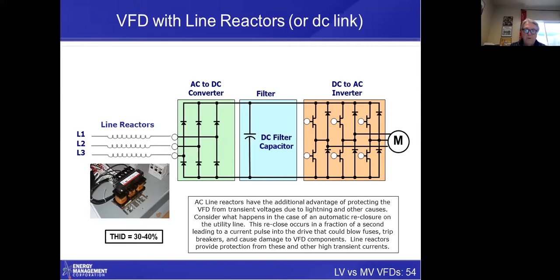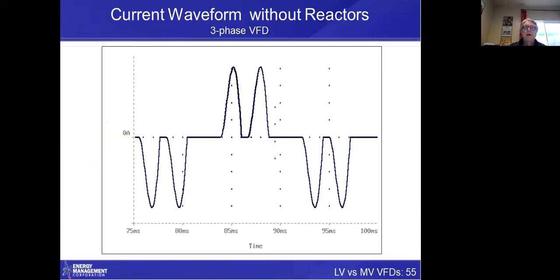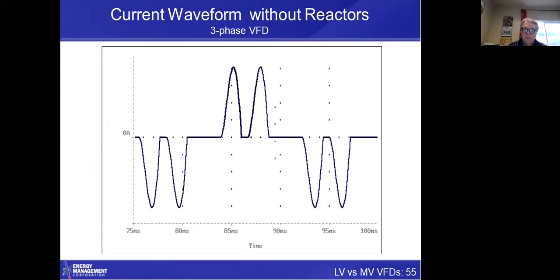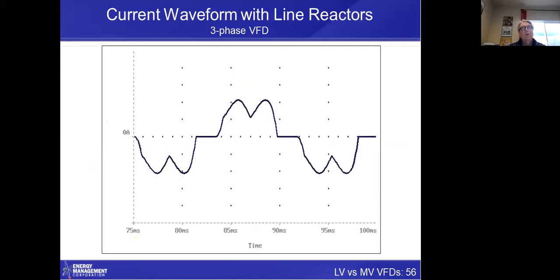They're cheap, they're easy, they can be used on any variable frequency drive. And I'm always preaching that. Here is without reactors. Here's the waveform with reactors. Now, I'm not saying that's a sine wave. It's not great, but this is 100% distortion. This is about 30% distortion.